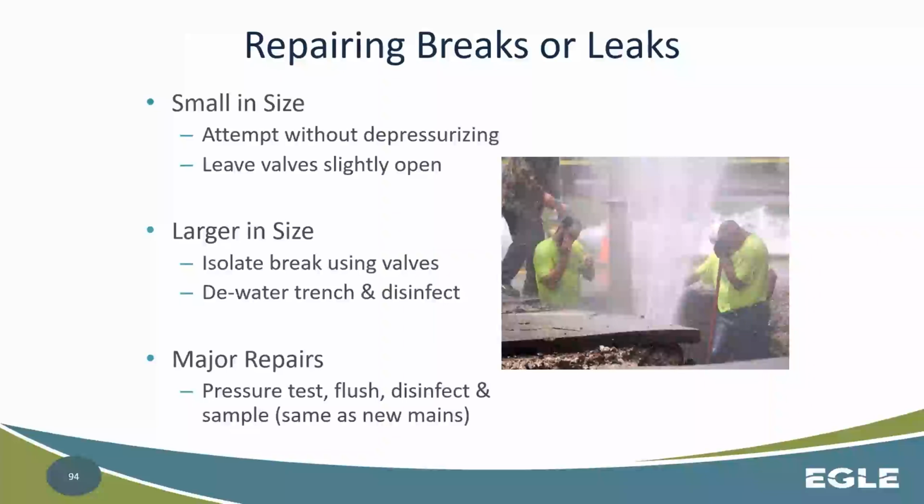Okay. Repairing breaks or leaks. So if you have a water main break here, all the situations can be different. If it's a small one, hopefully you can do that without depressurizing the system. Maybe you're closing the valve slightly just to decrease that pressure a little bit.